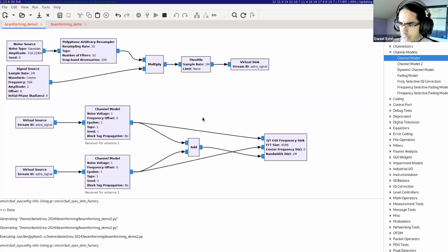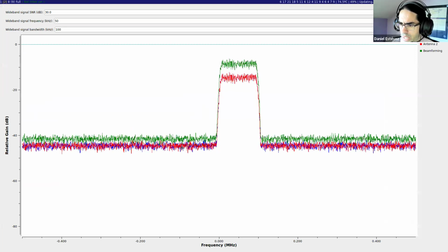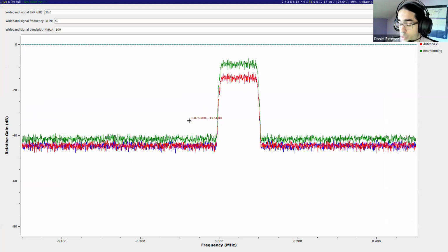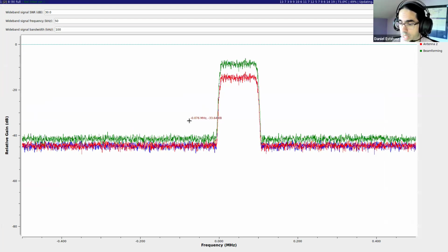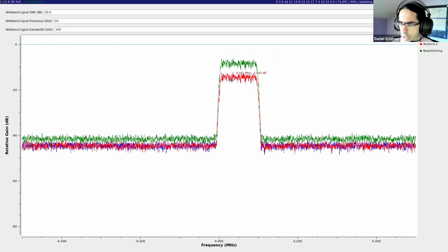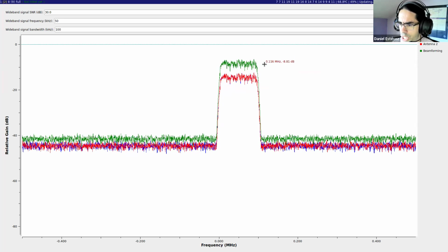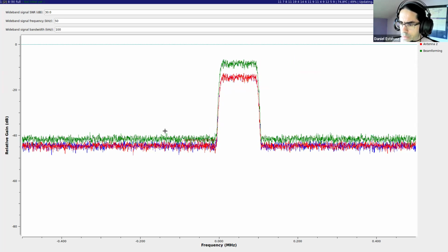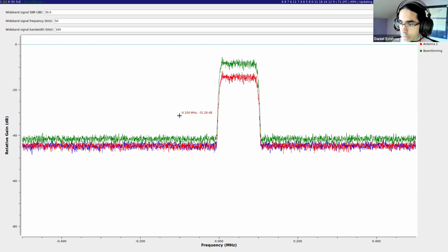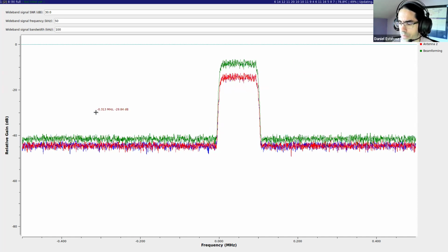If I do that, then I basically get a different normalization on the noise and on the signal. So if I divide by 2 after adding, basically everything goes 6 dBs down compared to what we're seeing here. So the amplitude of the beamformed signal wouldn't change, and the noise will decrease by 3 dBs. That's another way of looking at this. It's just a normalization of the amplitude.